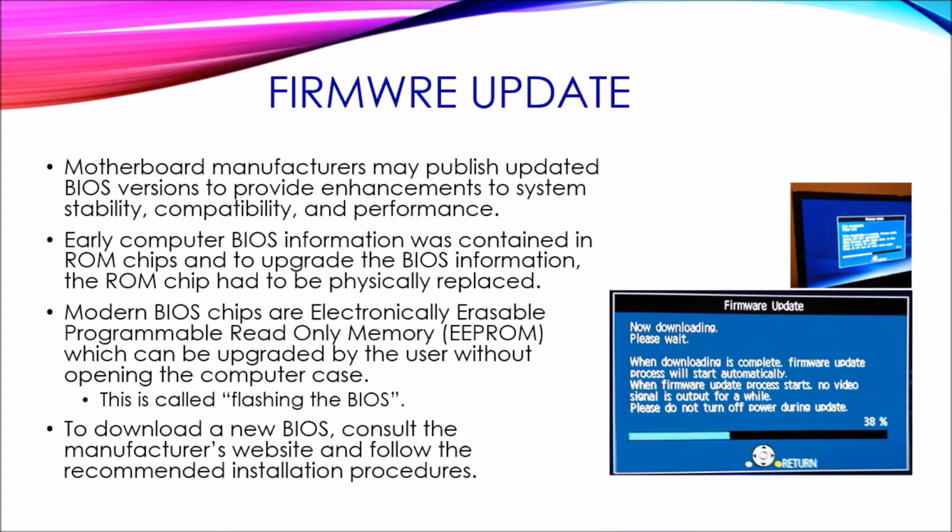To upgrade the BIOS information, the ROM chip had to be physically replaced. We cannot upgrade it by software. Modern BIOS chips or UEFI are EEPROM, electrically erasable programmable read-only memory, which can be upgraded by the user without opening the computer case.